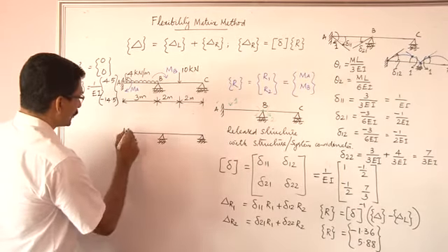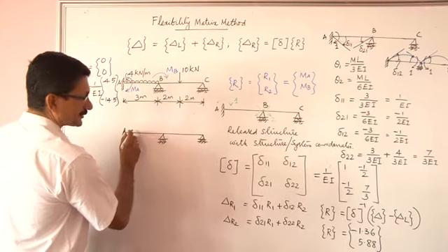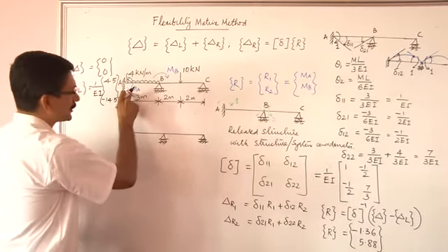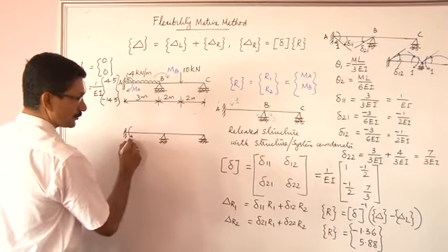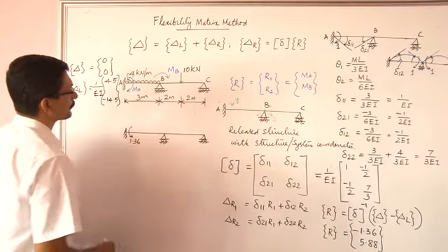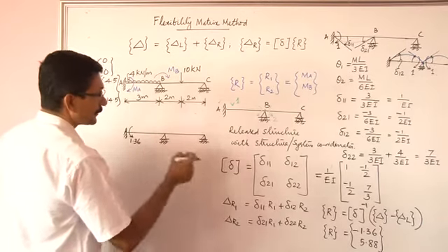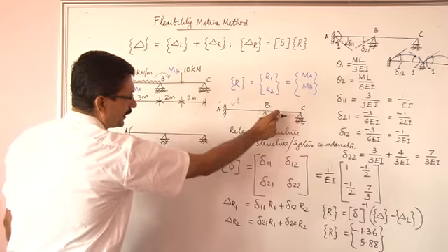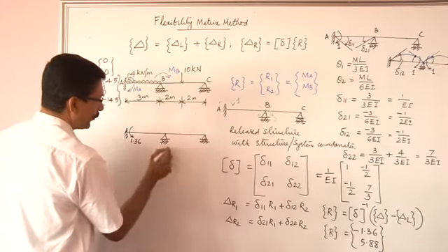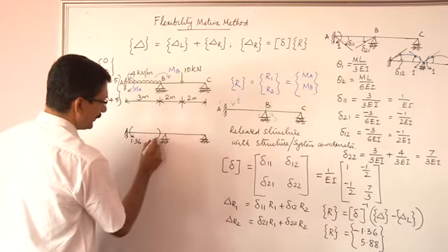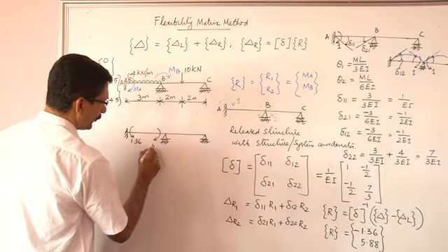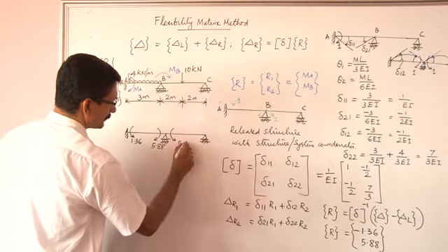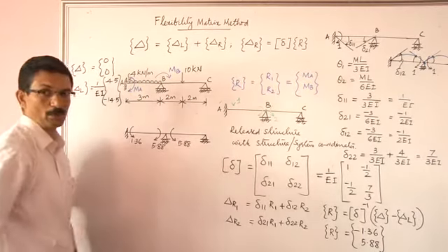If I plot that over here, minus sign represents anti-clockwise moment because this is chosen as clockwise. So this number is 1.36, and as per this coordinate system, clockwise here, anti-clockwise here are positive. So 5.88 is positive. That means this moment is 5.88 and this moment also is 5.88. These are the support moments.